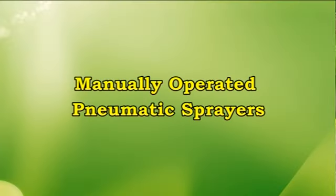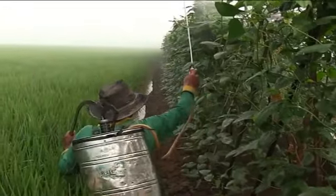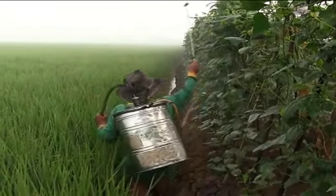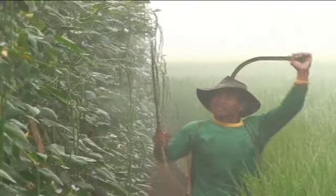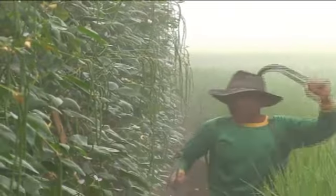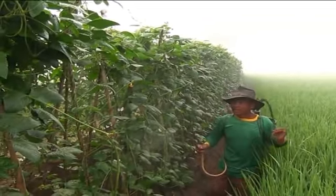Next is manually operated pneumatic sprayers. In the sprayer working with air compression system, the pressure is developed on the air contained in the spray tank. Hence, some air should be allowed to remain in the tank, which therefore should not be filled with spray fluid completely. They do not have agitators and hence are not useful for spraying materials which settle down quickly.